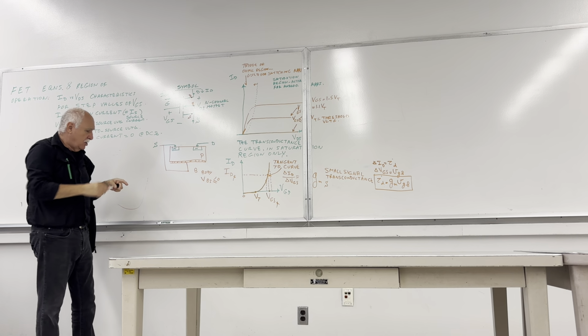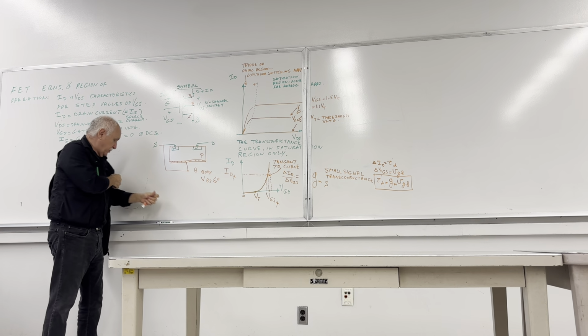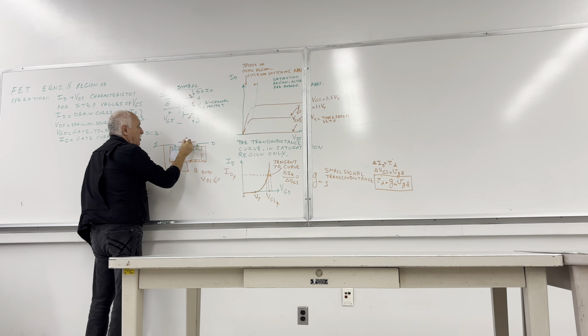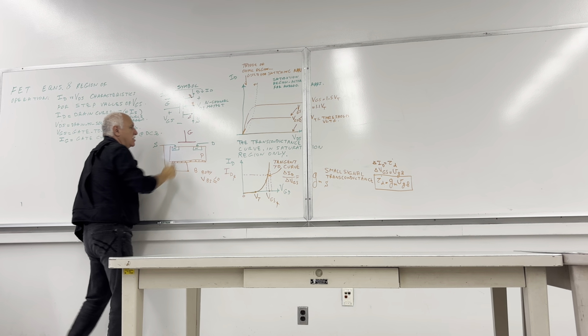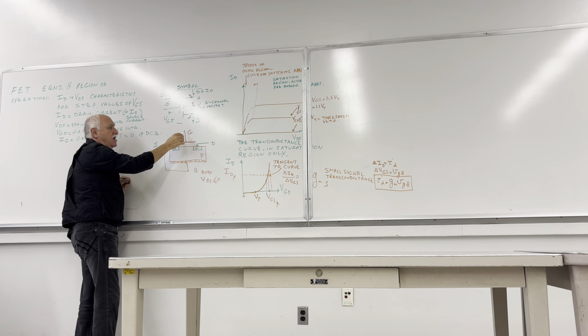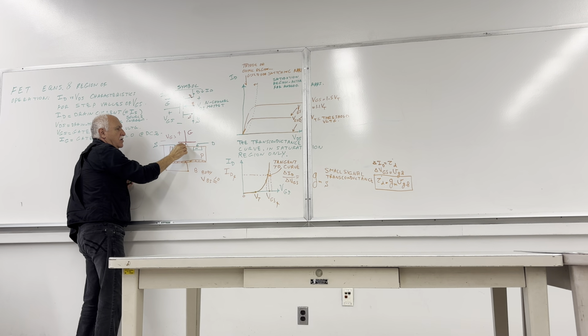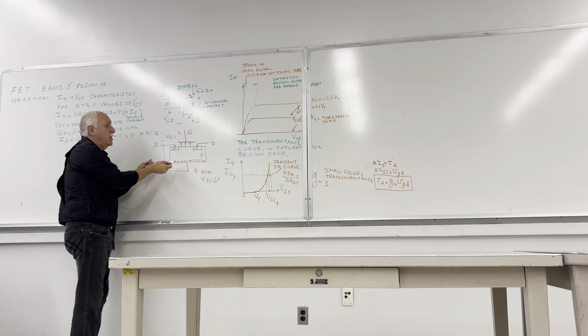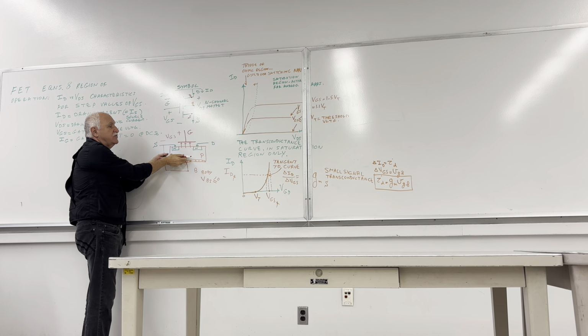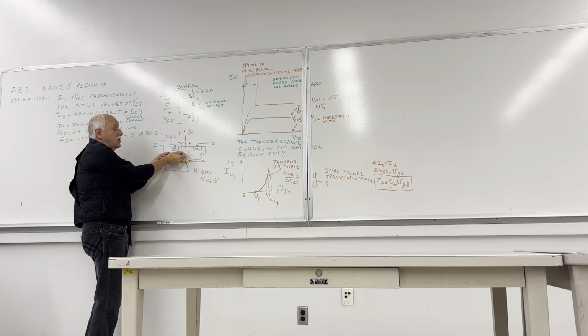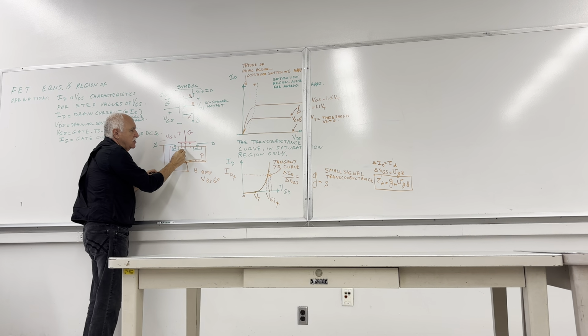Now, the next thing on that is the gate. Gate is at the top here. This is the gate. By putting a positive voltage on the gate, here, positive VGS, you create an electric field here, which will bring up electrons from the p-type material. First, it will create an inversion layer in here, and then it will enhance the number of the electrons just underneath the surface.